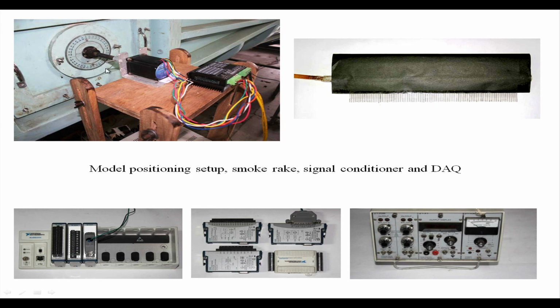So, therefore, it is always more convenient to hold the model from the side wall in such a situation, and then you can have say an automatic pitching arrangement over here, so that you can change its angle of attack from time to time. Here the angle of attack is being changed in a static sense.